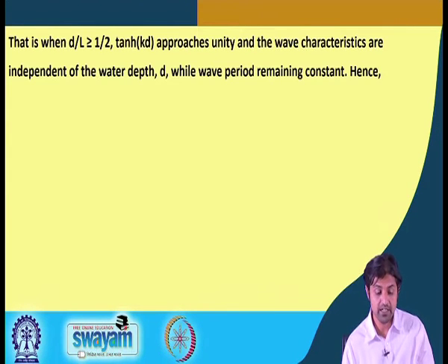When d by L is greater than half, tanh kd approaches unity and the wave characteristics are independent of water depth. One important thing to note is that the term d does not appear in this equation, because the term that contained d was tanh, and the tanh term goes to 1 in case of deep water. Therefore, all the wave characteristics are independent of the water depth. This is an important result. So, L naught in FPS is